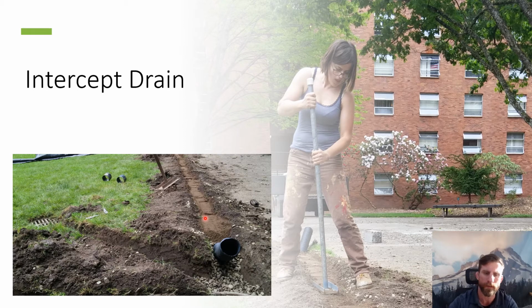So now we have reduced down the ability of water to drain through this system to about 1.5 inches per hour with the sand, because we put sand over top of the gravel. Okay, and that's an example of an intercept drain tile system. And you see here, the idea is water will move across the native soil to the drain tile here, or across this sidewalk to the drain tile, where it can then move more rapidly through the drain tile here, which is then going to be tied into this catch basin over here where water can collect.